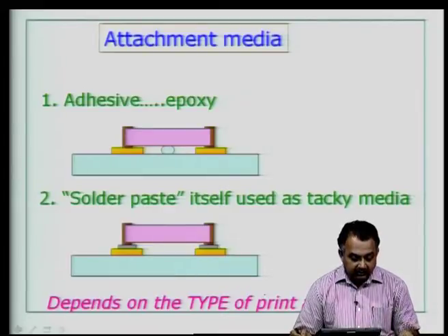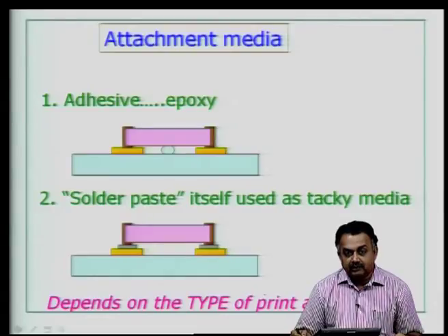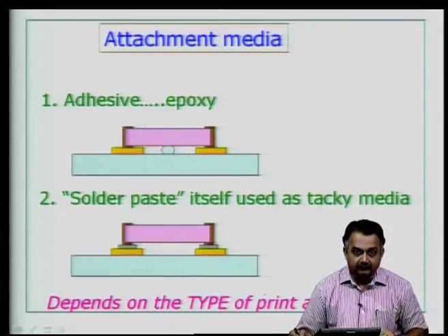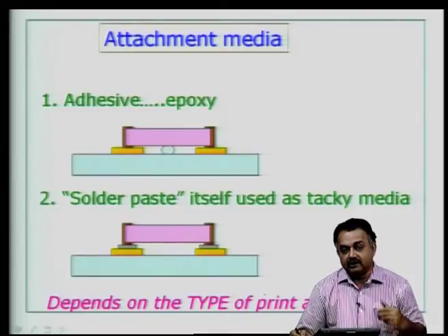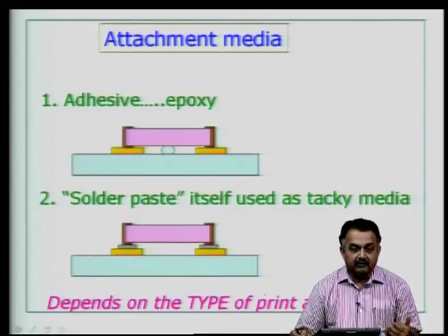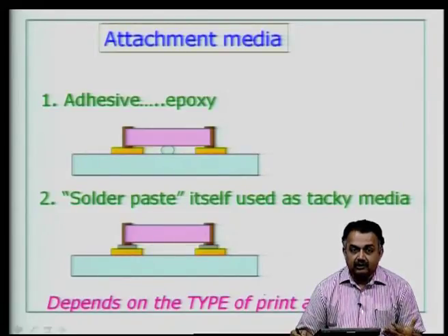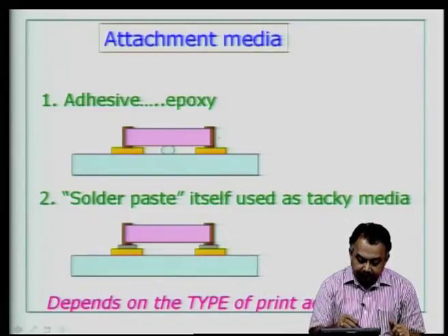Now, let us look at some of the other processes typically used in a reflow soldering process. We must know about the attachment media, right. When a surface mount device, whether it is an active device or a passive device, has to be attached to a substrate, then you have to use an adhesive. So, typically we use adhesive, which is again epoxy based.